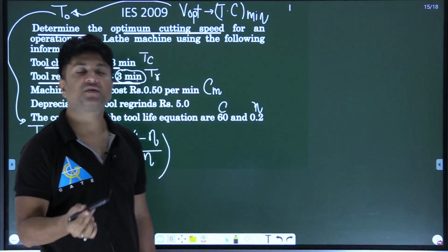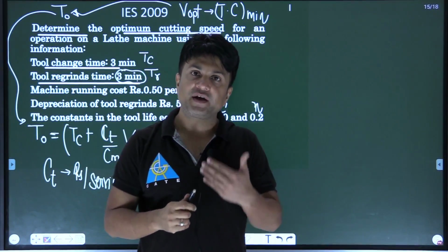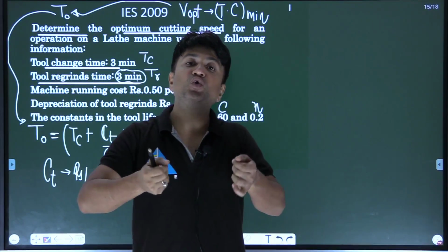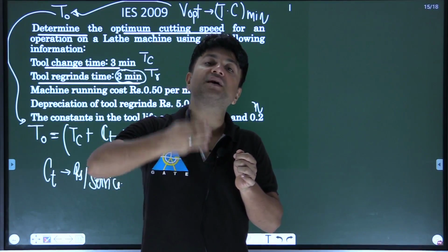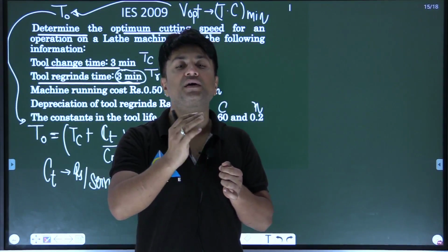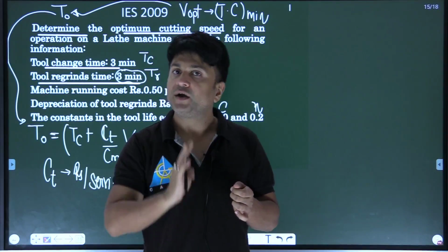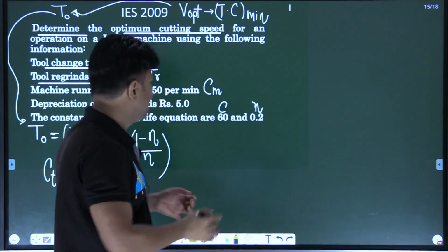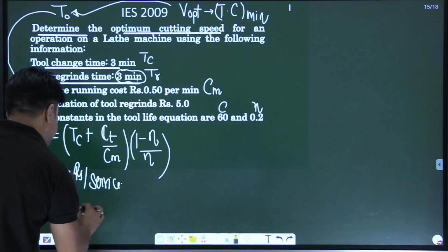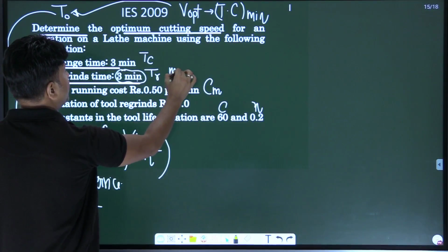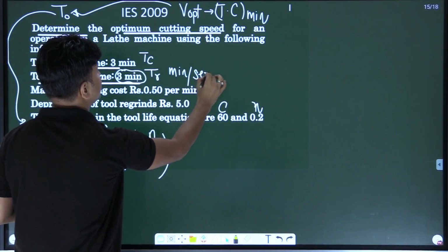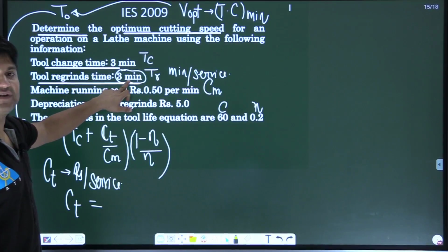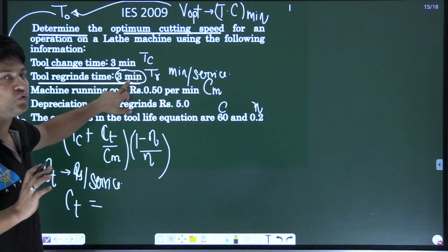And during service, basically when the tool is worn out, when the flank becomes worn out, when the cutting edge is worn out a little bit, we do a grinding operation to make the flank perfect, to make the cutting edge perfect. So, it is basically a machining operation. So, CT, basically, is the cost up to that minute you are providing the service. This is the service time. After that the tool is perfect, and after that the tool is ready to use.